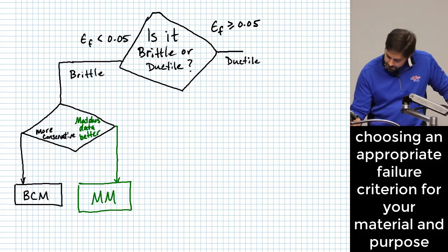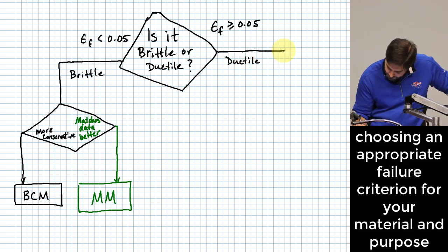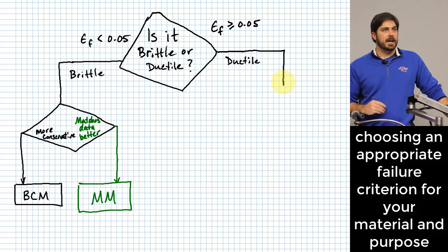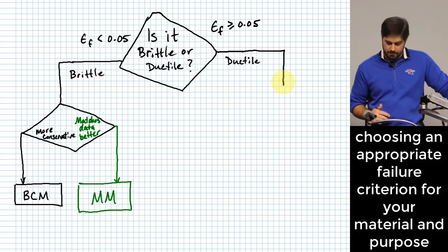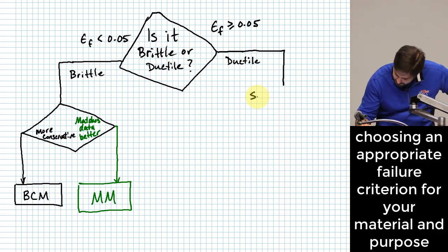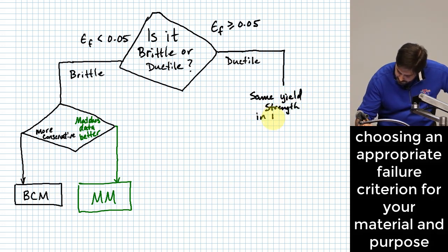Okay, over on the ductile side, the first question we've got to ask is, do we have symmetric strength properties? Same yield strength in tension and compression.